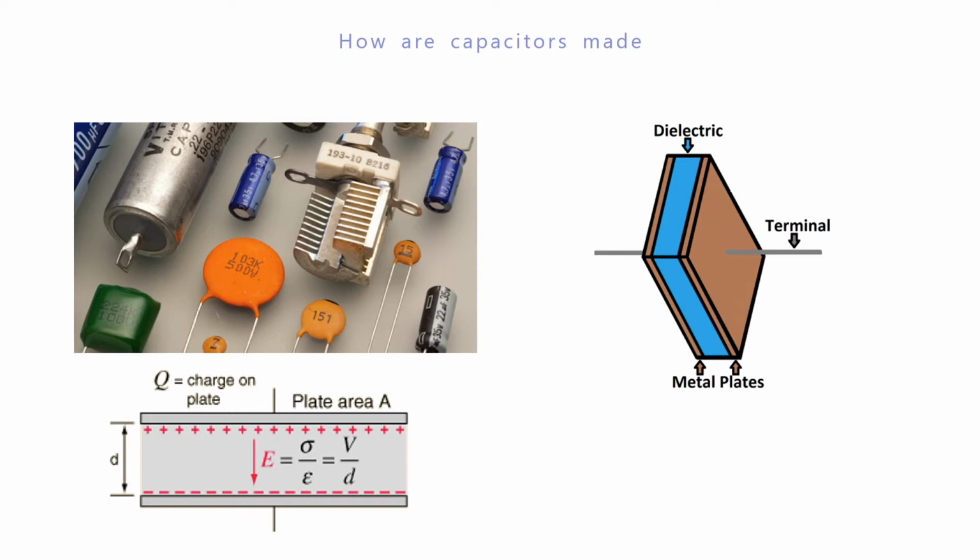The total capacitance of a capacitor can be calculated with the following equation shown here. ER is the dielectric's relative permittivity, a constant value determined by the dielectric material. A is the amount of area the plates overlap each other, and D is the distance between the plates. With all these three variables known, you are able to calculate the total capacitance of the capacitor.